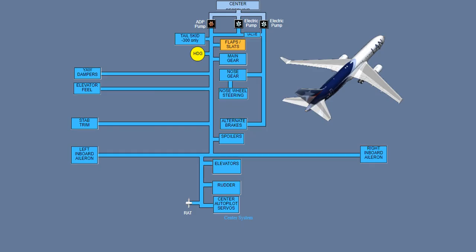Hydraulic-driven generator. In a situation where the hydraulic-driven generator is the only remaining generator electrical power source, hydraulic power for continued hydraulic-driven generator operation is primary. Therefore, hydraulic flow to the slats and flaps is reduced, resulting in increased slat and flap operation time.